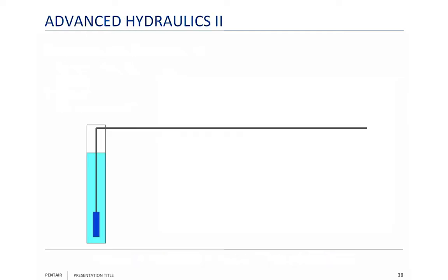Now, why am I telling you this story? What does it mean to you? All right? What it means to you is this. About 22 years ago, I got a phone call from a guy, and he said to me, Bill, I don't understand this. He says, I'm using a 70-gallon-a-minute submersible pump to sprinkle with. Okay? He says, but I'm having a problem. Every 3 months, 3 feet from the wellhead, I'm popping a hole in the top of the pipe.